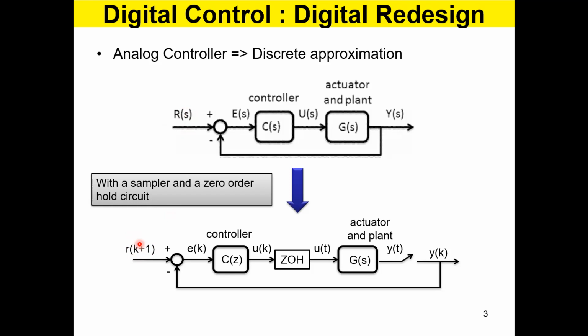You can have a continuous value, but what comes to the system is discrete samples of that waveform. If the output is operating at 1 hertz, the input also has to operate at 1 hertz. Every second, for a brief moment, you command the controller with the reference value. Even if you keep it continuously, it doesn't matter, but the controller will take it only once every second.